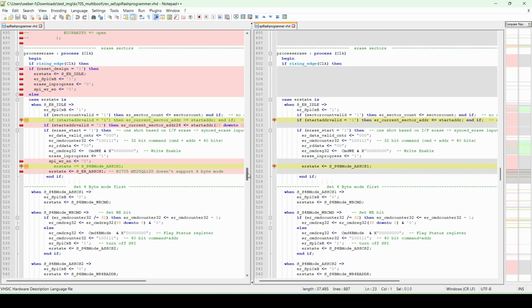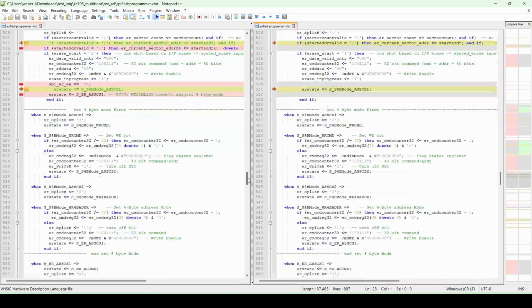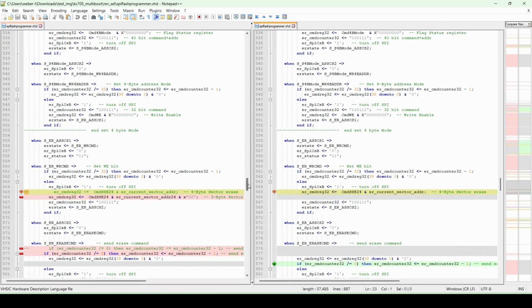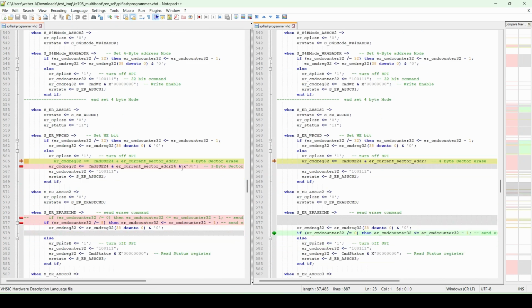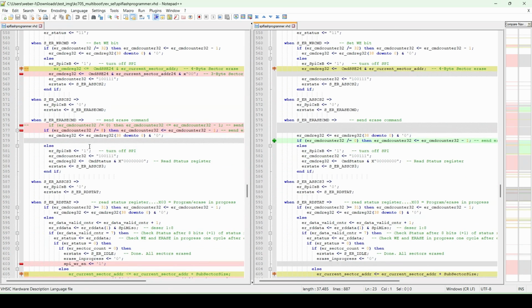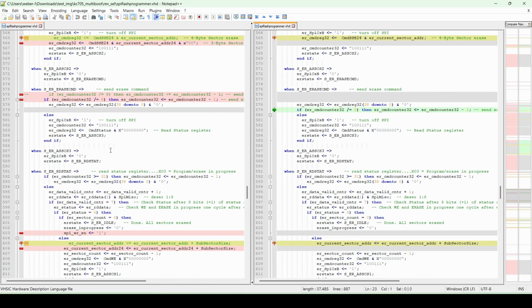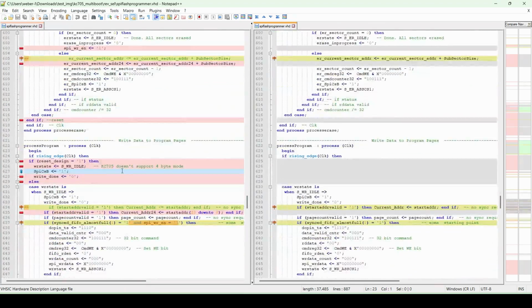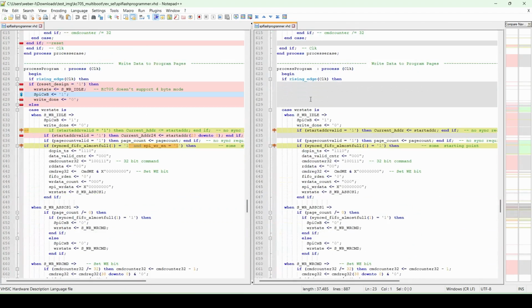The UltraScale boards use the newer SPI device that supports the 4-byte mode, but in KC705, the SPI memory doesn't support the 4-byte mode, so we bypass the 4-byte mode feature and directly go into erase and write using 3-byte addressing. The application note is also mainly to demonstrate how the warm boot jumping is designed. The code actually is not very robust.